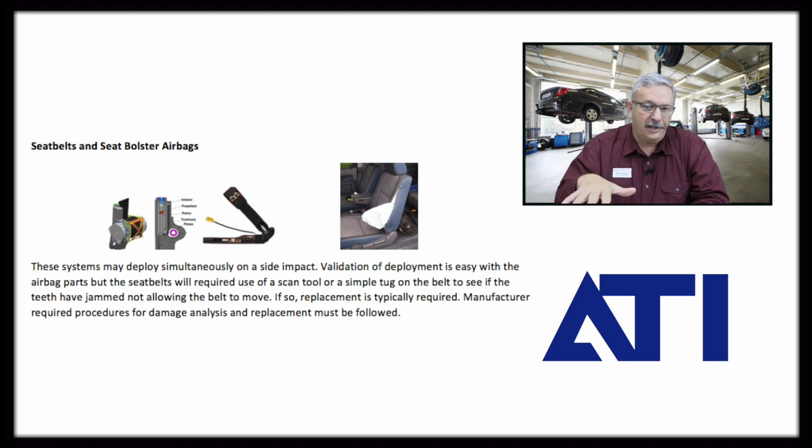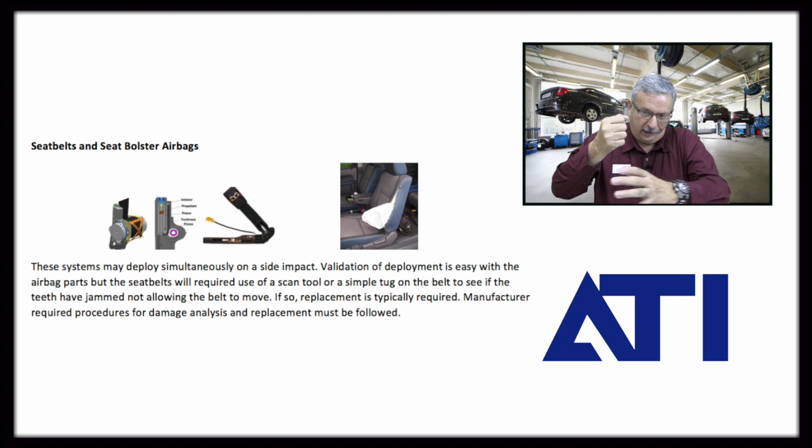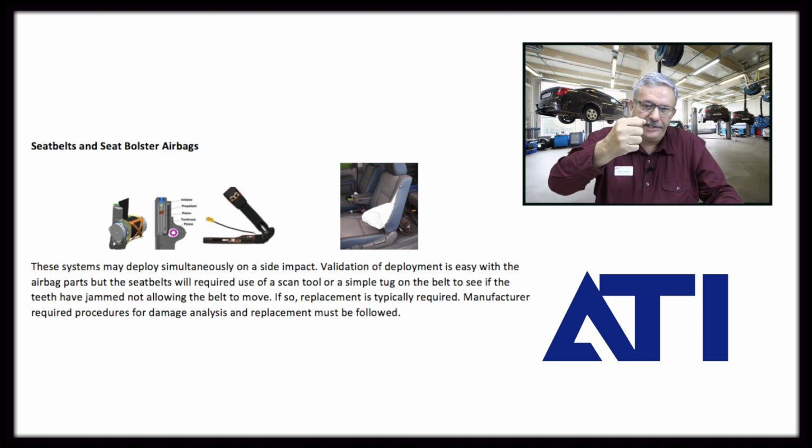So water comes up to the bottom of the door, it's already above where this retractor sits. So it's worth taking off the molding, looking down inside with a flashlight and seeing if there's been any moisture down in that area. Again, the self-diagnostics for the system should tell you if there's going to be any issues, but there's nothing wrong with just doing a visual inspection and checking.